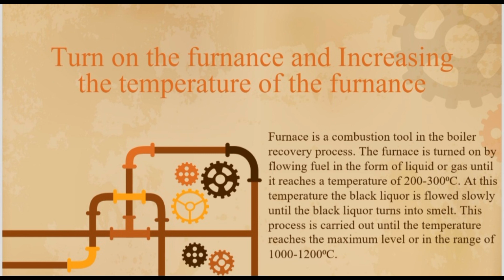Once the temperature has reached the desired level, the fuel flowing into the furnace is stopped and the black liquor that is flowing is slowly opened completely so that the combustion process is maximized and more efficient. That's all the explanation for me about turn on the furnace and increasing the temperature of the furnace. Thank you.